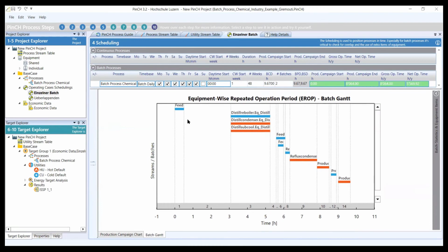And you can see this characteristic of a batch process that comes through is that we have heating and cooling requirements that exist on their own and do not overlap with other heating and cooling demands for direct heat recovery. There is a possibility to do so around the distillation column, which would be something that should be investigated. However, with this time-dependent behavior where there's no overlap in most of the other heating and cooling requirements, this is an indication that thermal energy storage is an opportunity that could be used here to increase heat recovery.